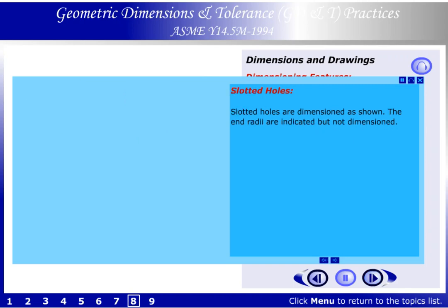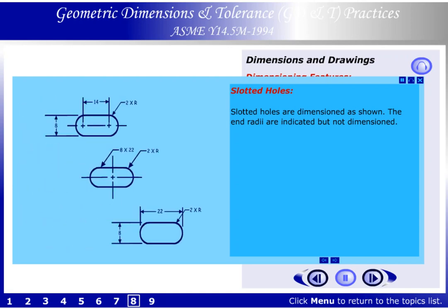Slotted holes. Slotted holes are dimensioned as shown. The end radii are indicated but not dimensioned.